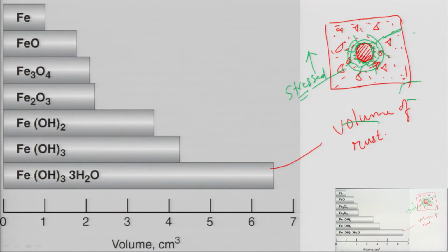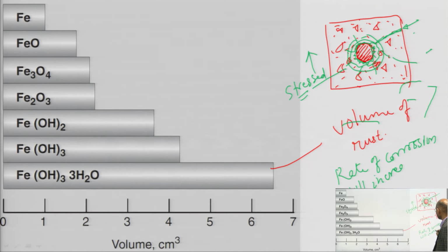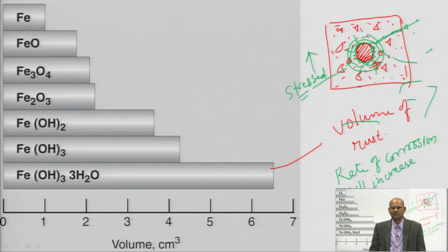So, how is this corrosion going to occur? What is the main important phenomenon? You need some materials: you need oxygen, you need moisture, water, and sometimes you need chloride also. These agents will find more access to the concrete surface. More moisture will go in from here, more oxygen and more chloride will be supplied here, and the rate of corrosion will increase. Initially whatever the rate was, at a further stage the rate will increase.